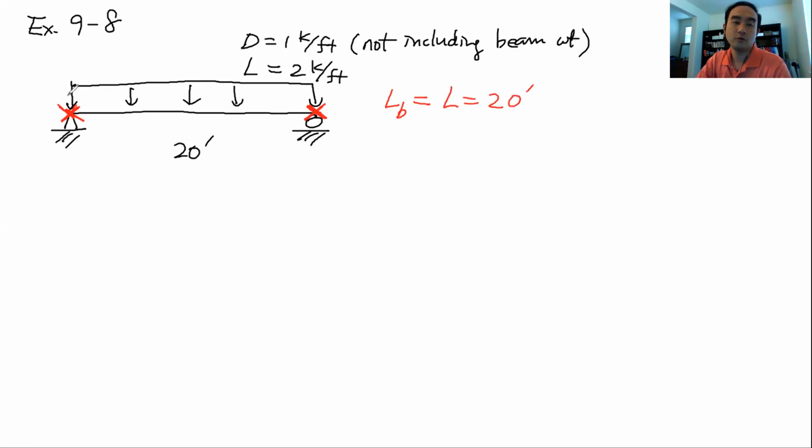Okay, if this entire beam is going to be braced in the lateral direction through the slab, for example, like in one of the previous example problems, then Lb is going to be 0. Depending on how often we have lateral bracing, that will determine the unsupported length. In this case, since we only have the lateral bracing at the supports only, then Lb is going to be equal to 20 feet. Okay, and I also said the Cb is going to be assumed as 1.0.